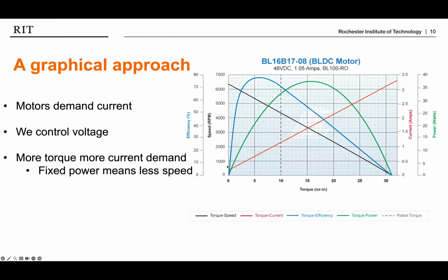So really quickly, if I can get my free running speed and my stall torque, and I can get my current at both of those points, I actually have everything I need to, at the most basic level, figure out how this motor is going to work.